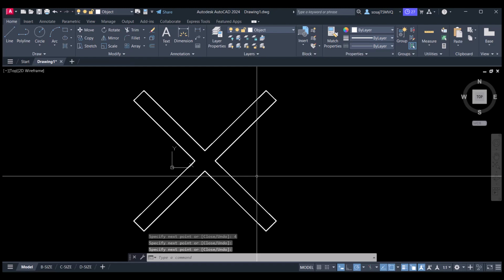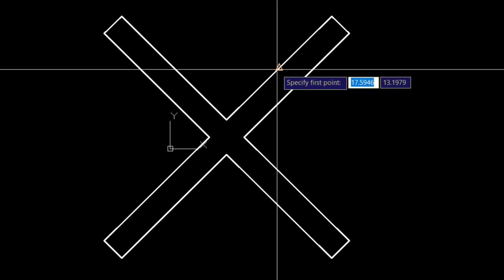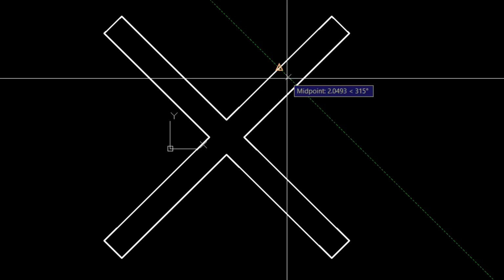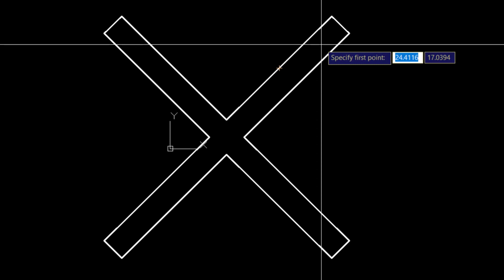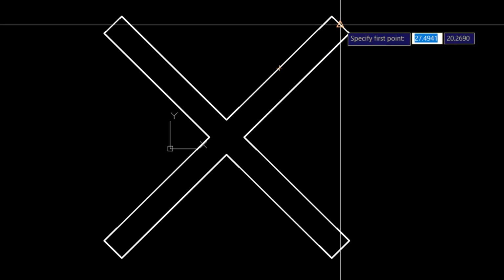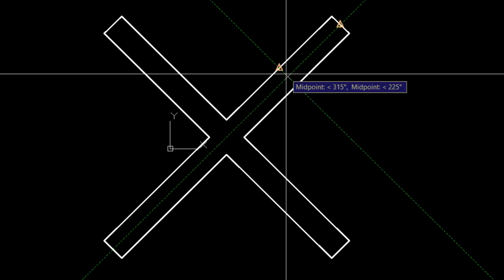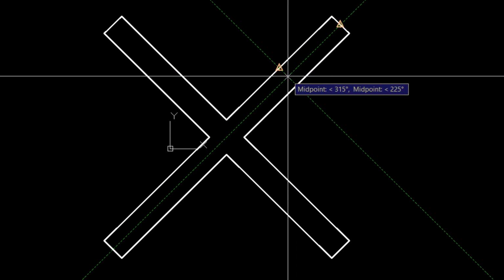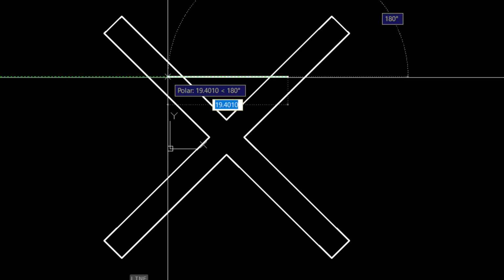Next we're going to draw the rectangle. I'm going to press enter to restart the line command, and now I'm going to track the midpoint of one side, and then track, you see the plus sign there, so I acquired that midpoint, and now the midpoint of the 4-inch length side. Move away, I'm tracking it, and right there in the intersection I'm going to click to start my line, and we're going to repeat that process 4 times.